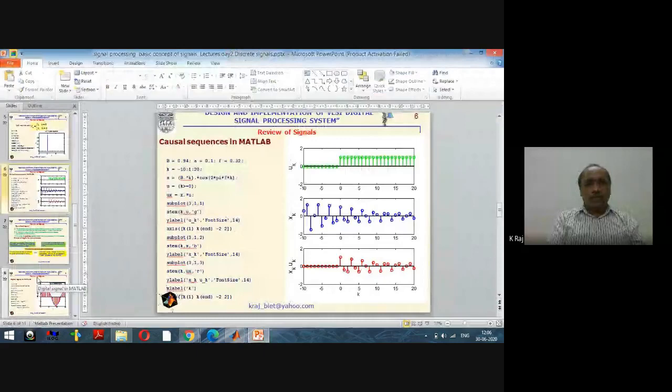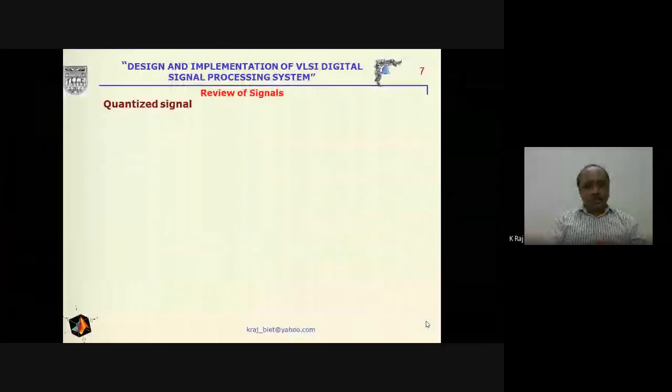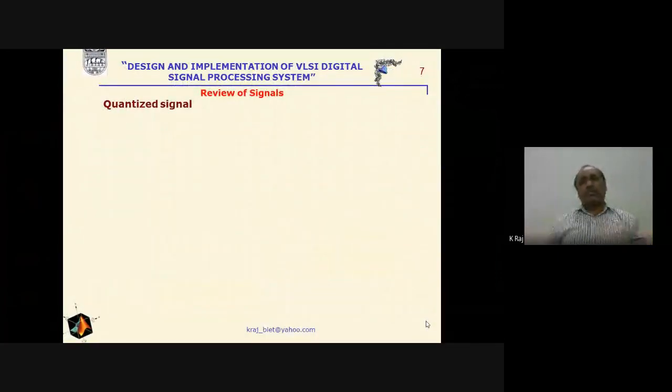After this one we are coming to the next point, that is related to quantization. Yes, so far we have discussed the discretization of any function. Discretization means whatever analog or continuous time signal was considered, it was discretized only in the time domain, or we can say we have passed those signals through a switching function, and the switching time was selected as capital T here.